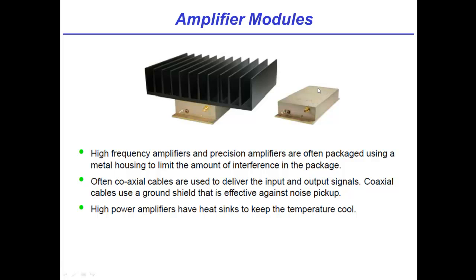So amplifiers also have some odd packages, right, Vivek? Yeah, that's right. In particular, amplifiers are used in a range of applications that may place constraints on the package. For example, many amplifiers are used in high-power applications. Your audio amplifier might be a high-power application. Now, when used in a high-power application, the amplifier internals generate a lot of heat. So we need to find a way to dissipate the heat such that it doesn't cause the amplifier to overheat and burn up. And that's commonly achieved using a heat sink.